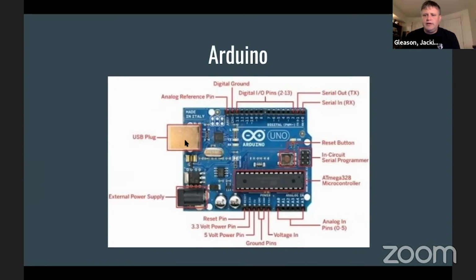Another thing to talk about, which I kind of forgot to mention: if you notice on my robot, I'm using a cell phone battery as the battery supply. As long as it's a 5-volt cell phone battery, 5 volts or higher, you'll be able to use that for the Raspberry Pi board. And assuming you're not pulling too much out of it, it should be fine to also run the Arduino board off of it.